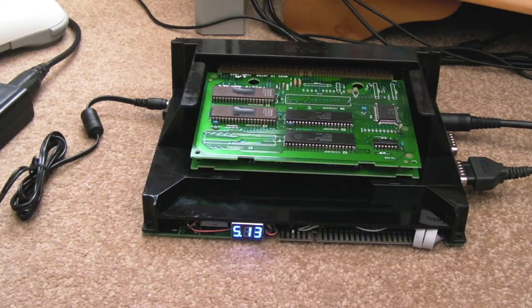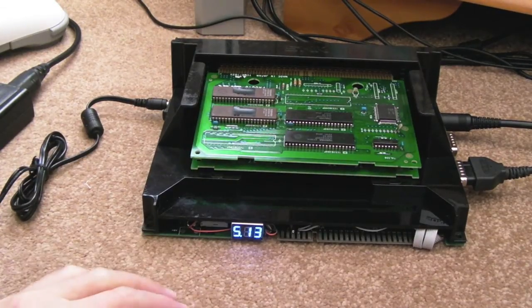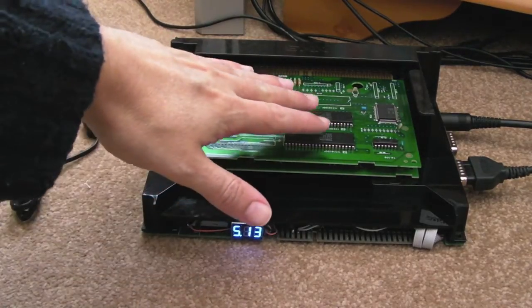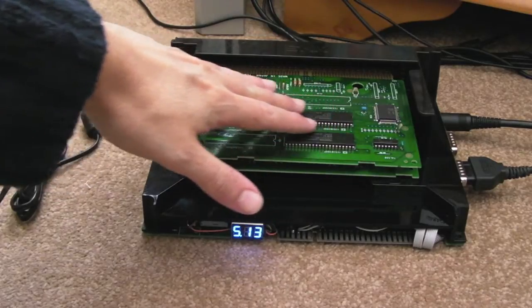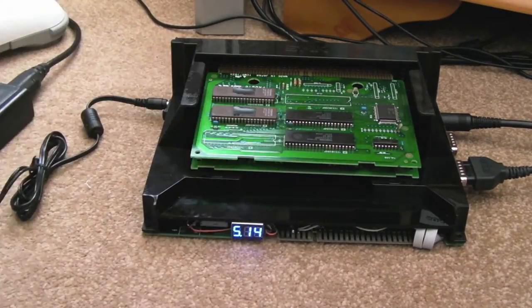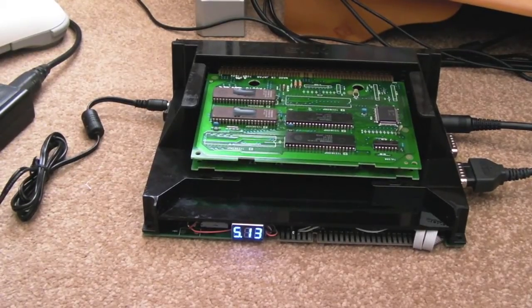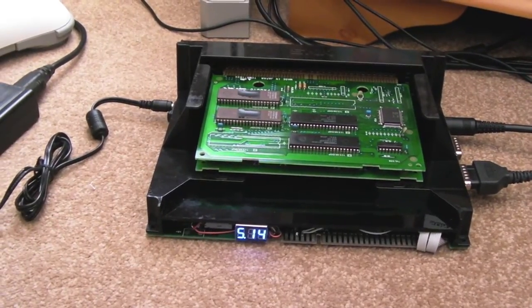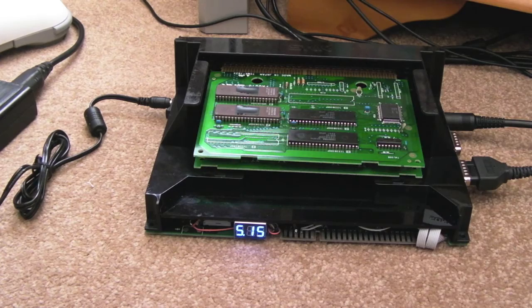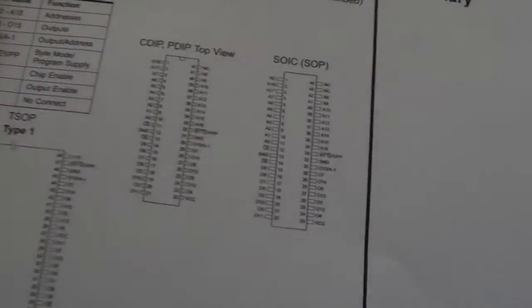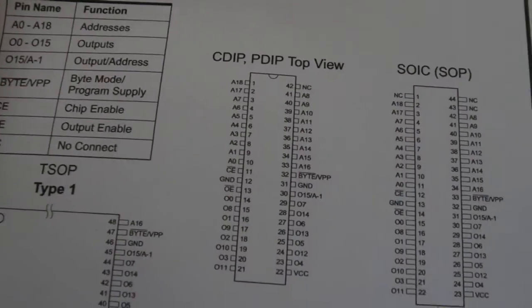So what I'm going to do is just check the data pins, because I was thinking about this. That's one of the first things I should have done really, just to determine whether it's the chips. A quick easy way of doing this with my scope, I'll show you. I've got the data sheet here for a pin compatible chip, so it's not the exact same chip.